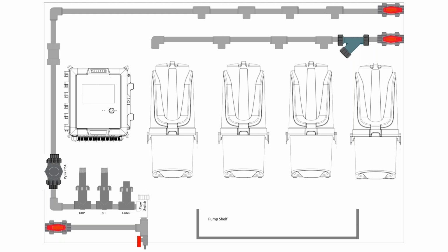The components I think are rated up to 125 or 150. But my rule of thumb is if you could get to 100 PSI or less, it just helps reduce hammer and other things you might experience. So if you're in a high pressure inlet, you may want to have a supplemental pressure regulator. The inlet assembly and all the components are rated for higher, but I'm conservative on that side, and I say 100 PSI, and you might want to regulate a little further upstream.